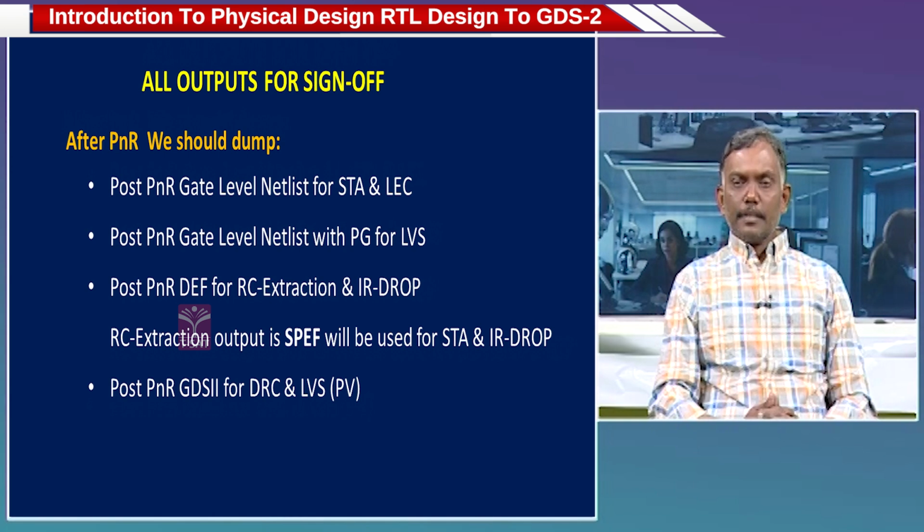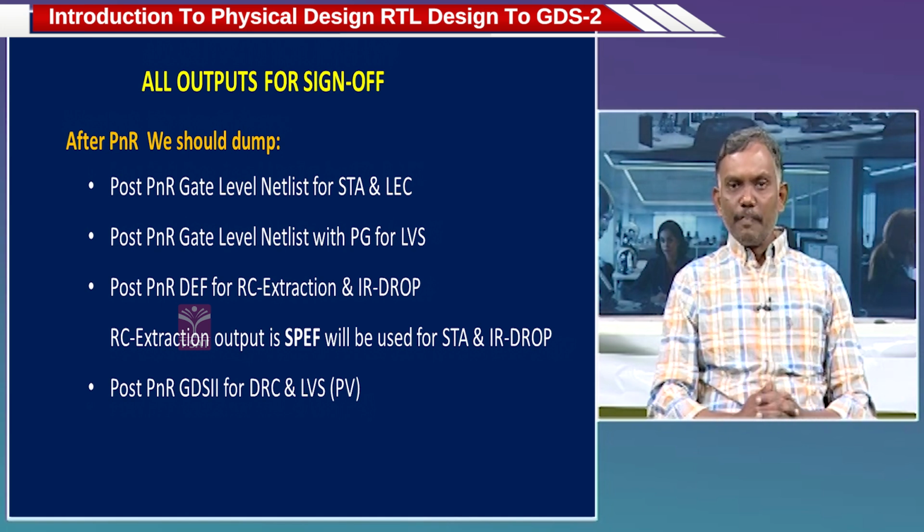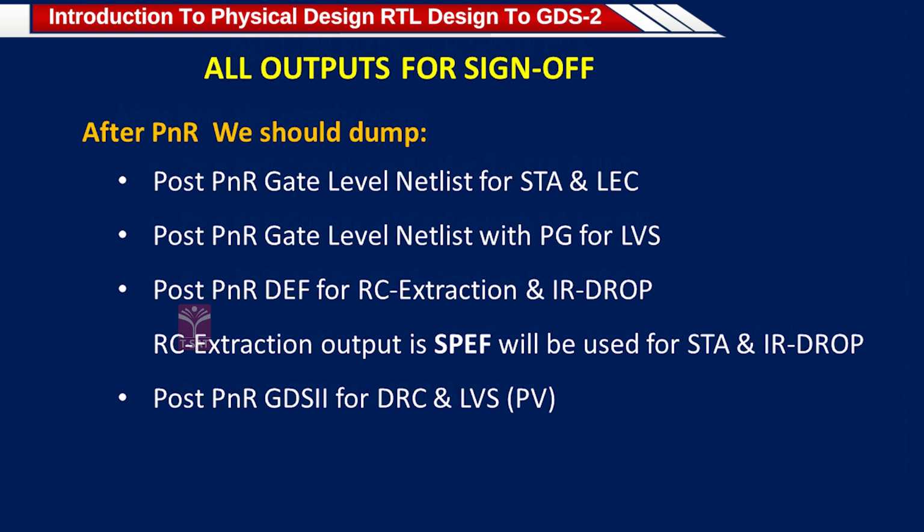And GDS2 is one more output file from the PNR tool, graphic design system, GDS. These are all different files for the different sign-off checks: STA, LEC, LVS, IR drop and PV, physical verification. I will explain in the coming slides.